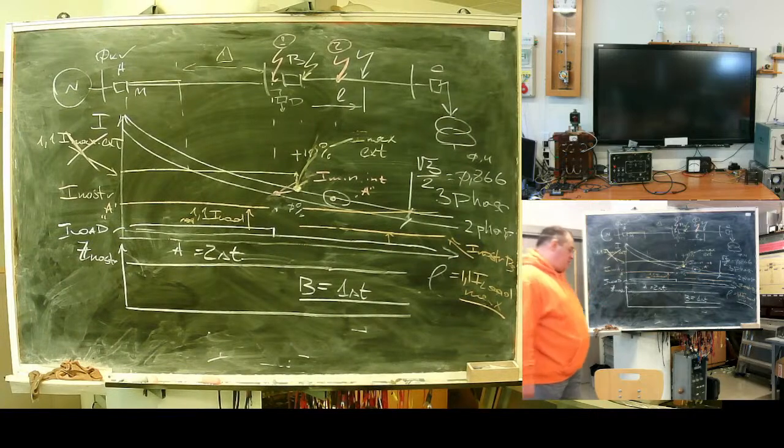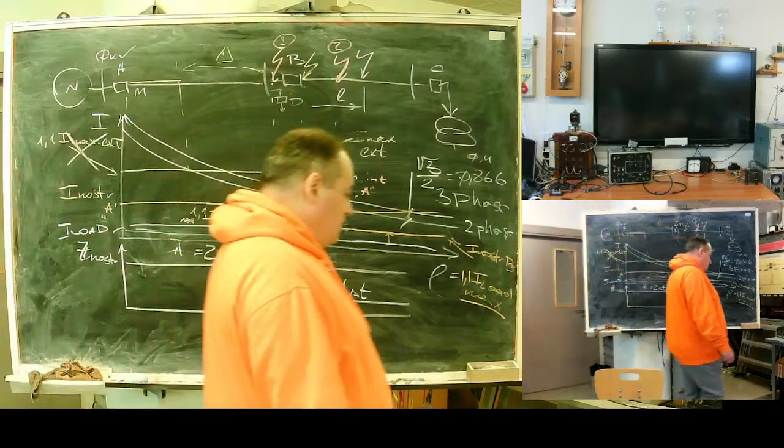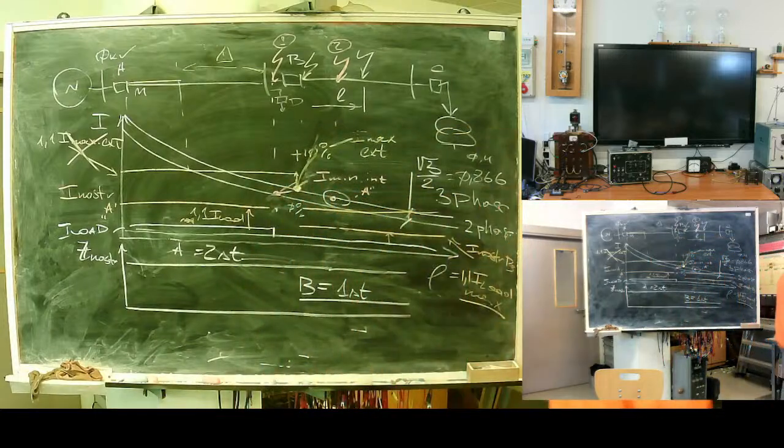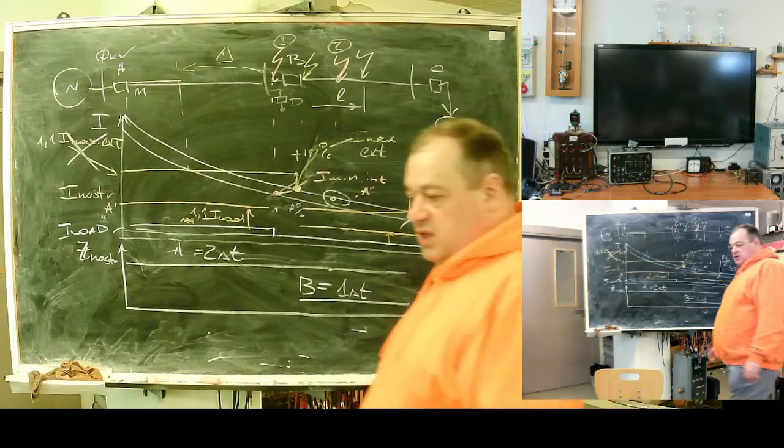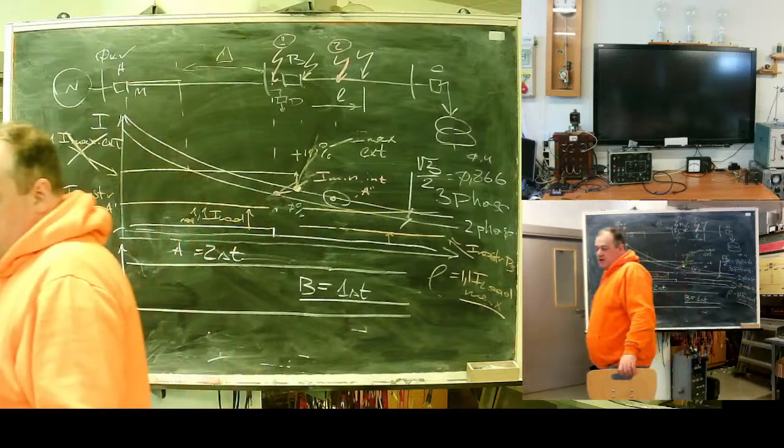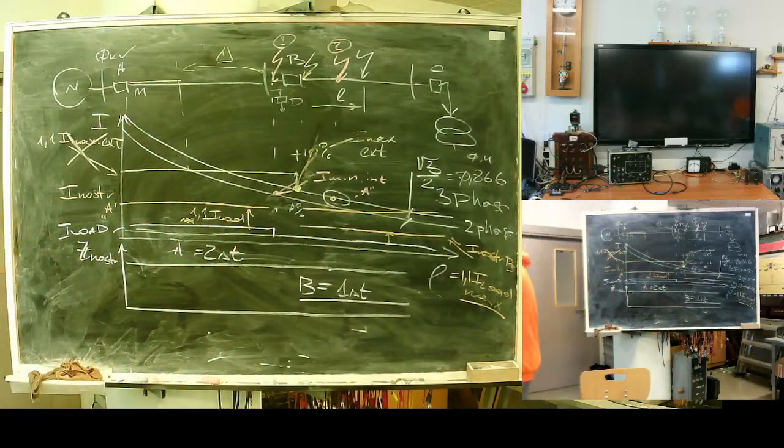Spacing of half a second fulfills any, except extremely archaic circuit breakers. If you have modern equipment, everything is fine, SF6 or better vacuum circuit breakers, or you can reduce time gaps to 300 milliseconds.